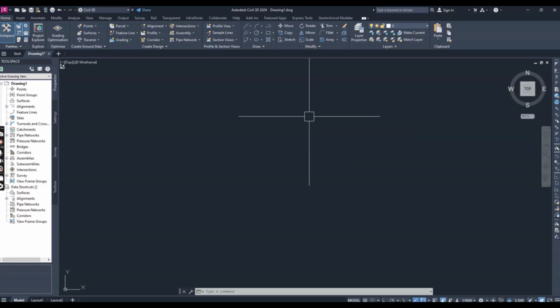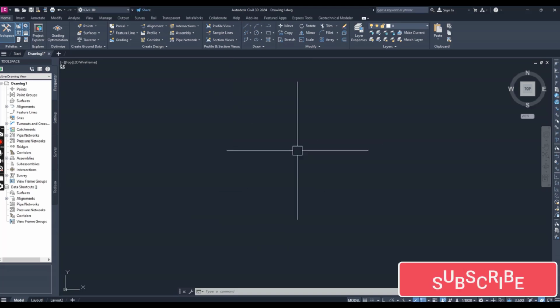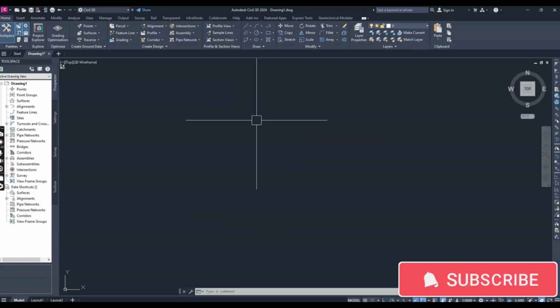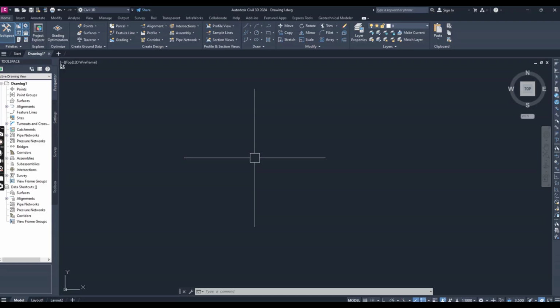The whole point of building a three-dimensional model is to include the elevation element that has been missing for years on two-dimensional plans, but to get there, designers and engineers still depend on the flat 2D representation of the vertical dimension, same like our profile view in Civil 3D. So a profile is nothing more than a series of data pairs in a station-elevation format. There are basic curves and tangent components, but these are purely the mathematical basis for the paired data set.